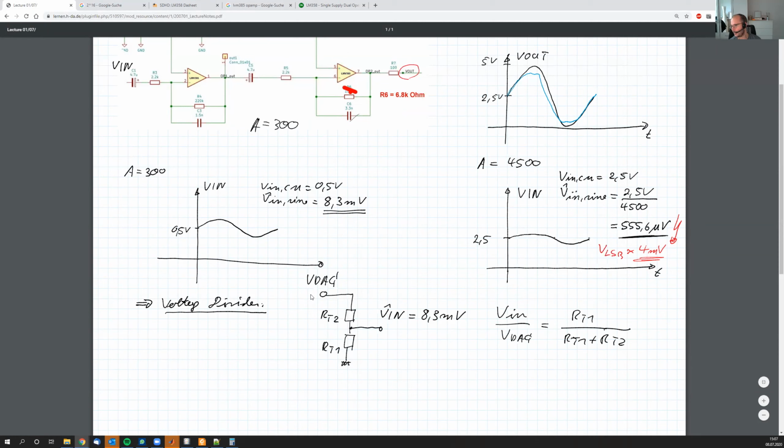But it will only have an impact if those values here are high. Yeah? So if you have a high resistance, then this comes into play. Yeah? If they are comparably low, then the other resistance here is not that important. But anyhow, check the data sheet of the DAC. There should be also electrical characteristics for that. No need to make rocket science out of that, but you should roughly have understood what's going on here. Well, but this is the specification for the output here.